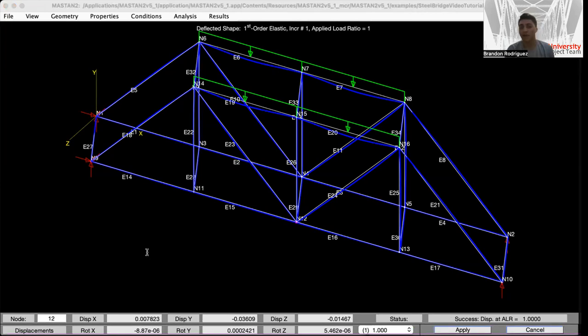And then this is more for later in the semester, but when we do optimize everything, some things to keep in mind. Consider section properties, the size, the shape, and the thickness of your members, your truss design, making small changes, like changing the section you're attaching to the diagonals as opposed to the other members in your bridge.